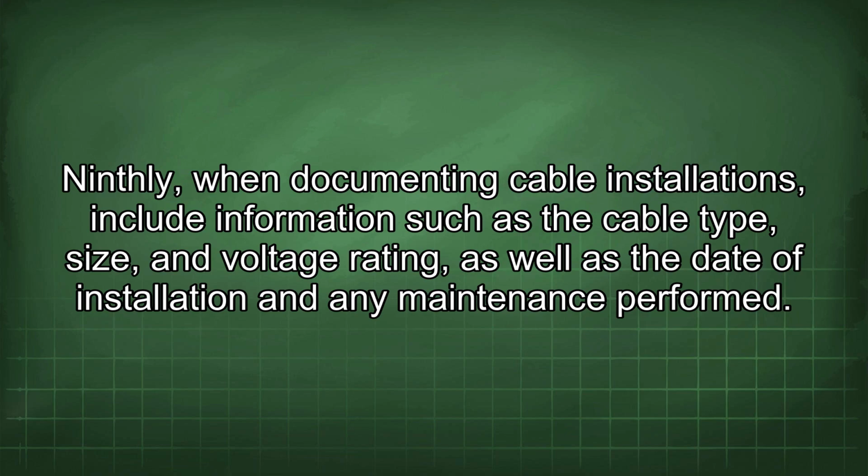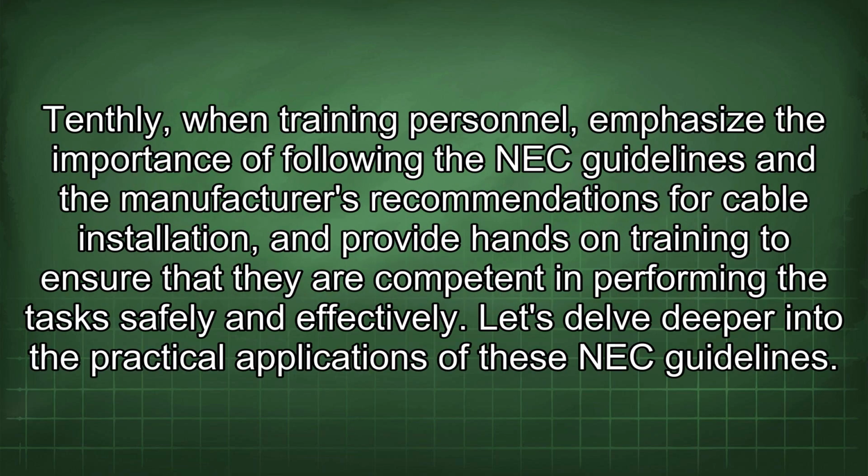Ninthly, when documenting cable installations, include information such as the cable type, size, and voltage rating, as well as the date of installation and any maintenance performed. Tenthly, when training personnel, emphasize the importance of following the NEC guidelines and the manufacturer's recommendations for cable installation, and provide hands-on training to ensure that they are competent in performing the tasks safely and effectively. Let's delve deeper into the practical applications of these NEC guidelines.